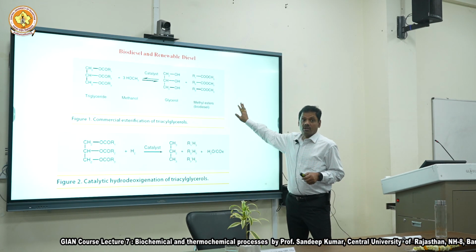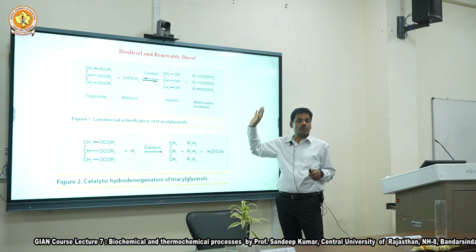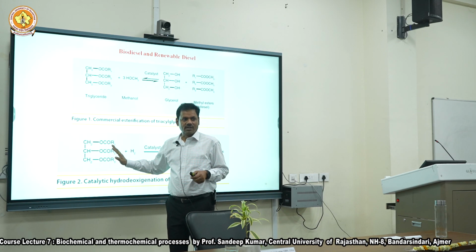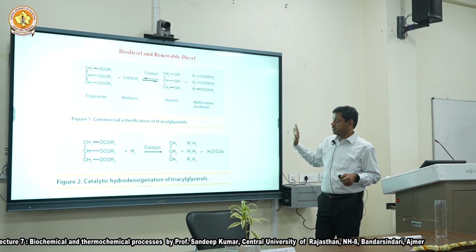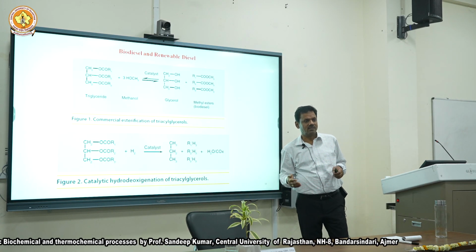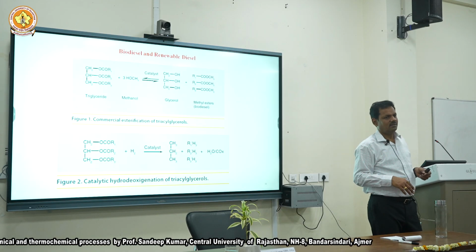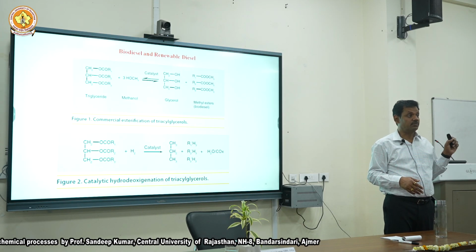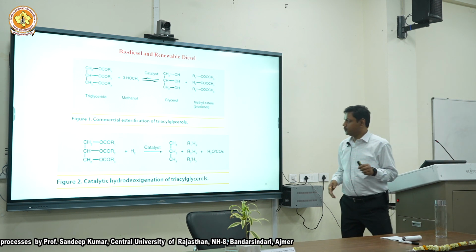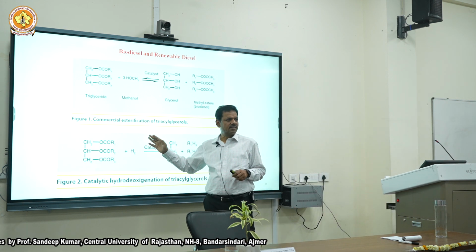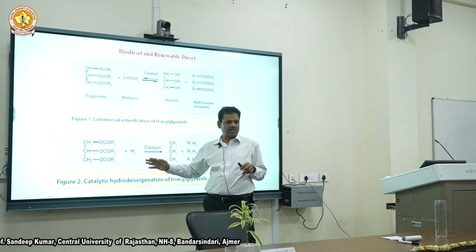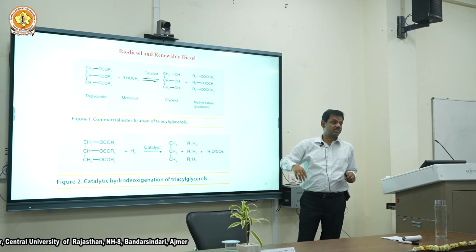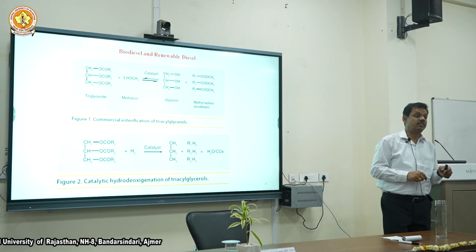This one is solving some problem, not entirely. We are looking for drop-in fuel. So can we take this, turn into diesel? Let's call it renewable diesel or green diesel, not biodiesel. Yes, we can do that. Remember, the hydrogen differentiate. So put hydrogen at least 300 degrees Celsius, around that. And you can turn it like a diesel straight. That is called renewable diesel.